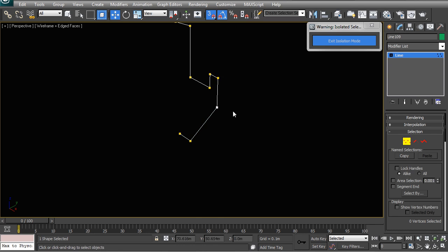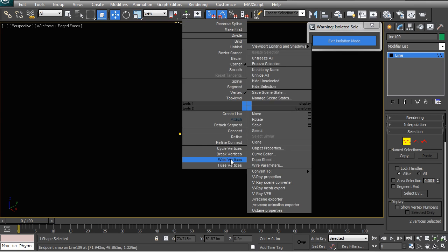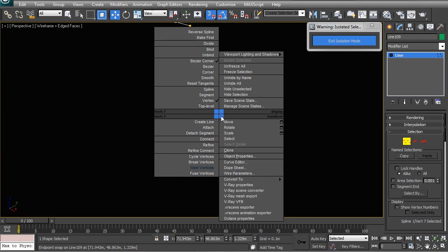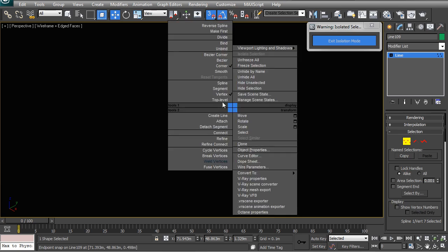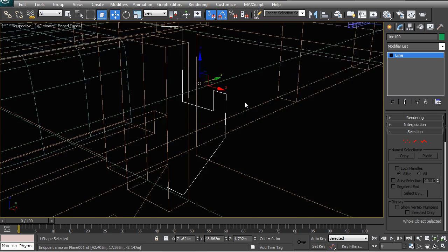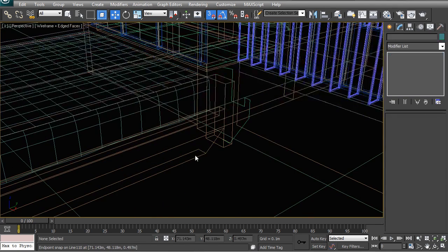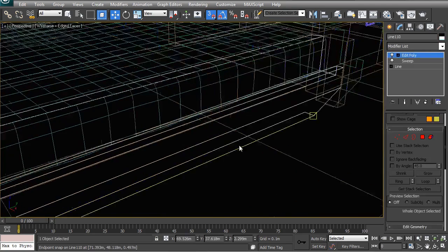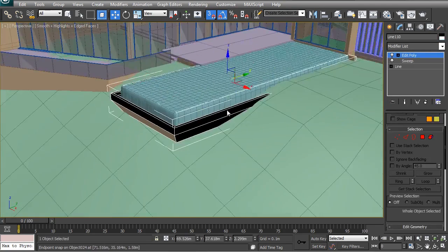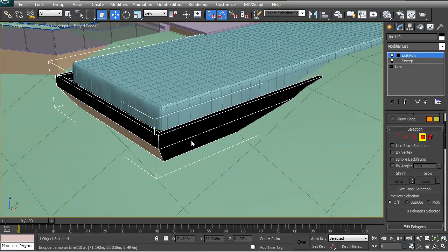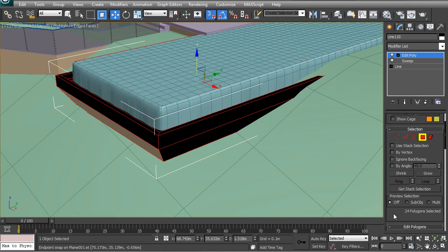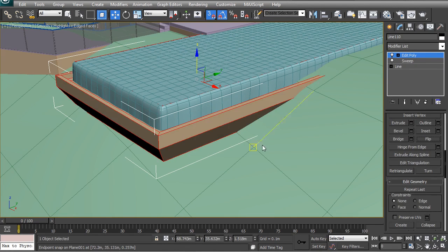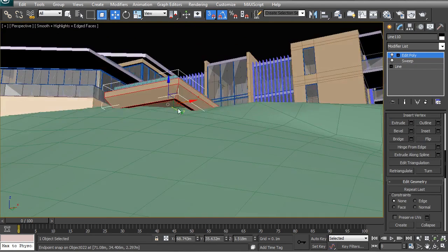After attaching, just select your vertex in this corner. You can see that there are two selected. Right click and weld those two together. Then you can right click and make sure that it's a corner. Once you release that, the entire object will be updated according to this profile. You may need to select all of your polys again, so let's just Control A on that, and let's flip all of those. You can see that now you have the underside.